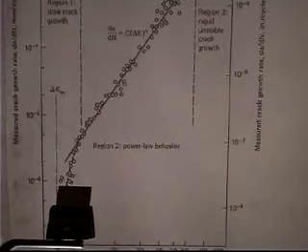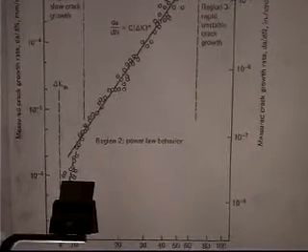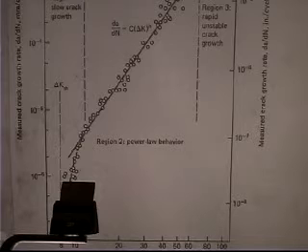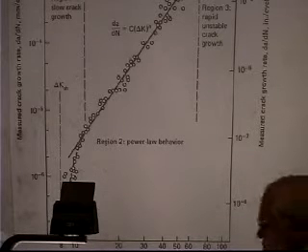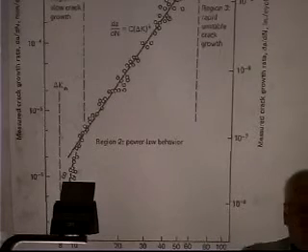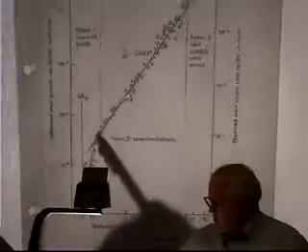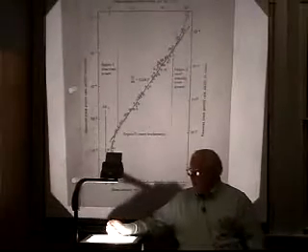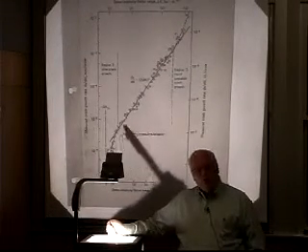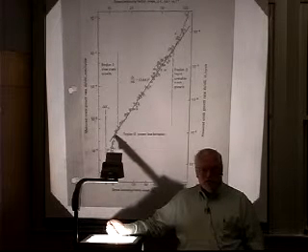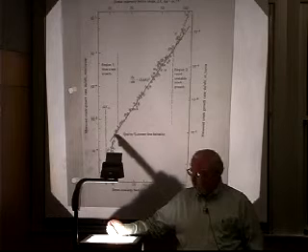Now, if I wanted to do the old SN type of curve, I might take 20 specimens, and some of them will be in that machine for 2 weeks, and some of them will be in there for 20 minutes, depending on the stress level I test. And there's a lot of scatter, so I want to run several specimens at each stress level. But I can generate my curve in 1 or 2 months' time with a lot of machining and replacing the samples. However, if I do this, I have a more precise sample to machine. So instead of paying $100 a sample, I'm now paying $1,000 or $2,000 for the machining of the sample.